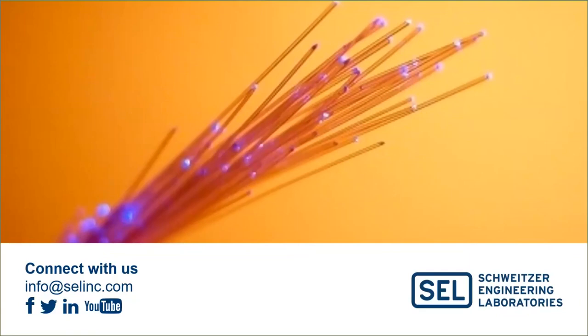Okay, what is meant by the term fiber over Ethernet? I think what we mean is Ethernet over fiber, because you can have fiber optics, and using our fiber optic serial transceivers, you can have 232 serial communications or 485 serial communications over fiber. But when we say fiber over Ethernet or Ethernet over fiber, we're talking about actually transmitting Ethernet data over the fiber optics. So the fiber optics themselves can be the same, but depending on what's on the ends, you could be transmitting Ethernet traffic or serial traffic. So hopefully that answers that.